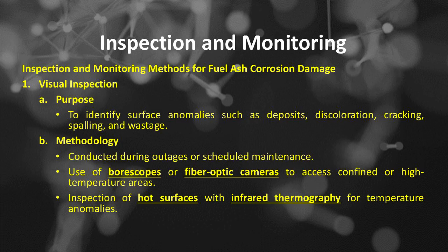Number A, purpose: to identify surface anomalies such as deposits, discoloration, cracking, spalling, and wastage. Number B, methodology: conducted during outages or scheduled maintenance. Use of borescopes or fiber optic cameras to access confined or high-temperature areas. Inspection of hot surfaces with infrared thermography for temperature anomalies.